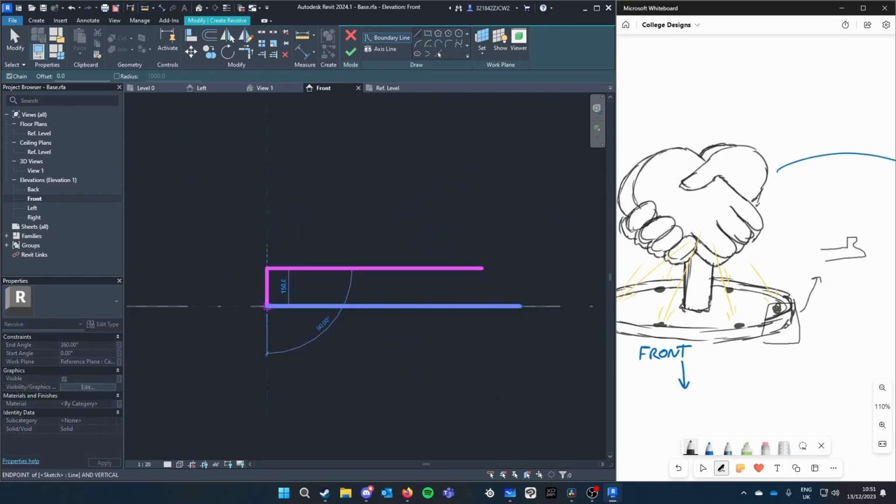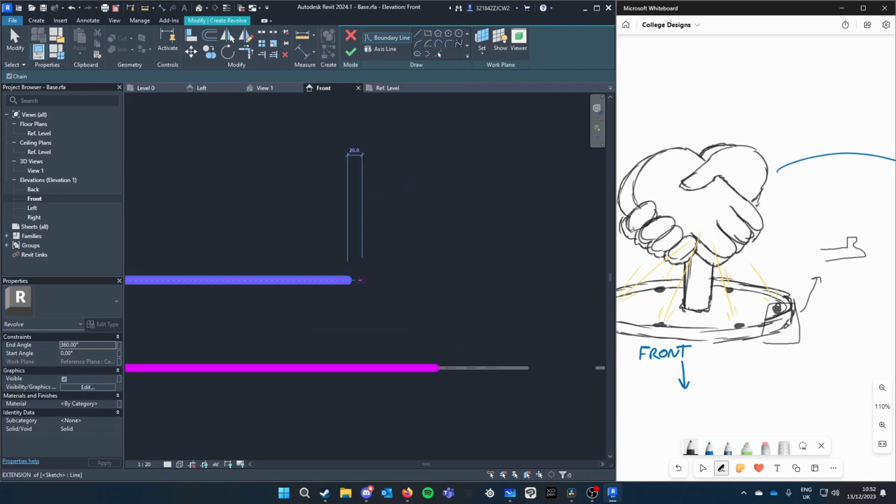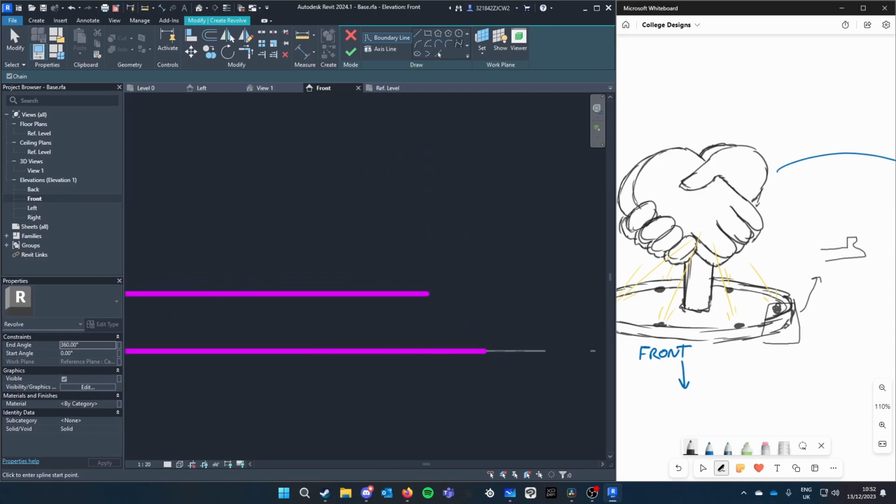So actually, first we're going to want to close this off on this end. This is the bit it's going to spin around. And then for the rest, we can use what's called the spline tool. So this will make a curve that is forced to go wherever our points go. It'll make it nice and fluid. All right, let's go for this.